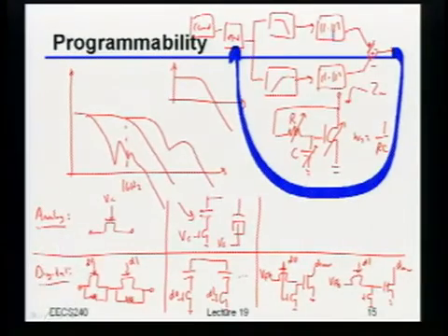Oh, no, okay, so this adaptive loop is usually really, really slow, because this is only trying to track the changes in the channel. Now, the channel does change: the humidity changes, the temperature changes, the mechanical stress changes, all kinds of weird stuff changes, but the good news is that's all way, way slower than multiple gigahertz. So this loop usually doesn't take too much power because it doesn't have to be fast. It doesn't have to respond to very fast changes. Again, great question. Other questions on this?